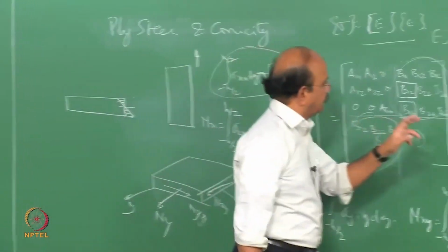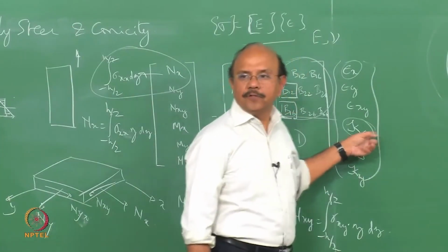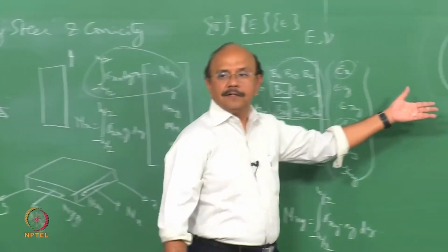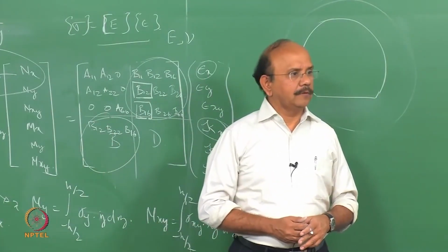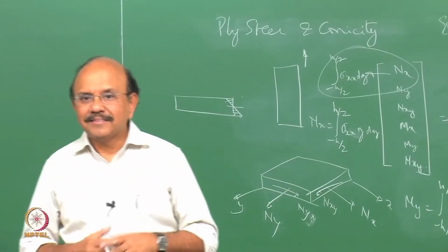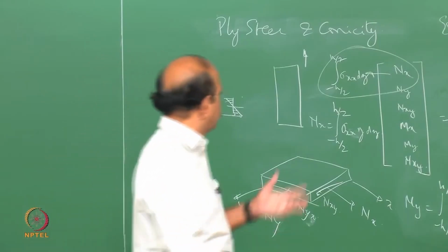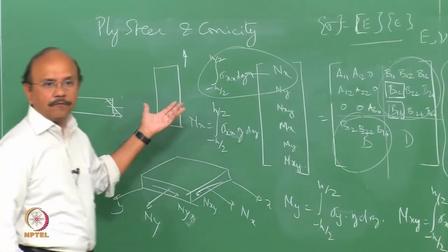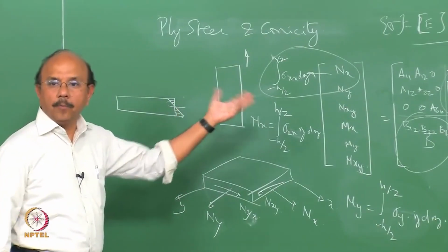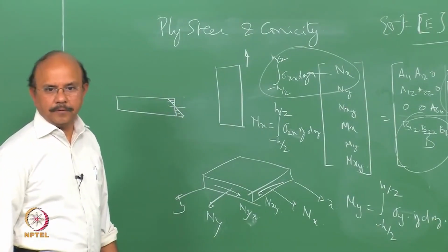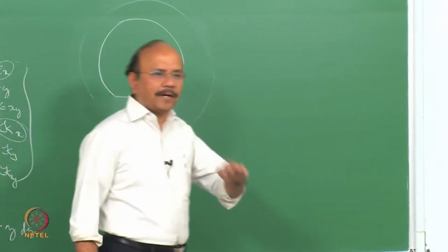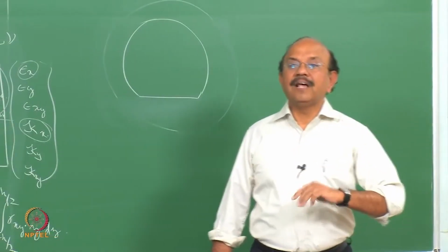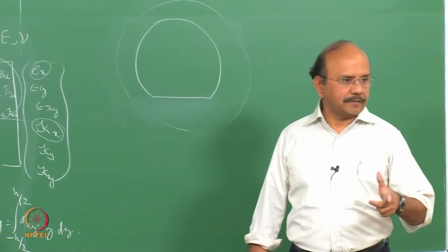Okay, let's come back. There's a lot more to look at. So kappa x I'm going to change now because I'm going to make it flat. When I make it flat, obviously I'm introducing forces. I'm introducing forces because of this coupling term. And those forces introduce the lateral force and a moment. So the simple fact that as the tire rolls on the ground and a part of the tire becomes flat results in a lateral force called ply steer.